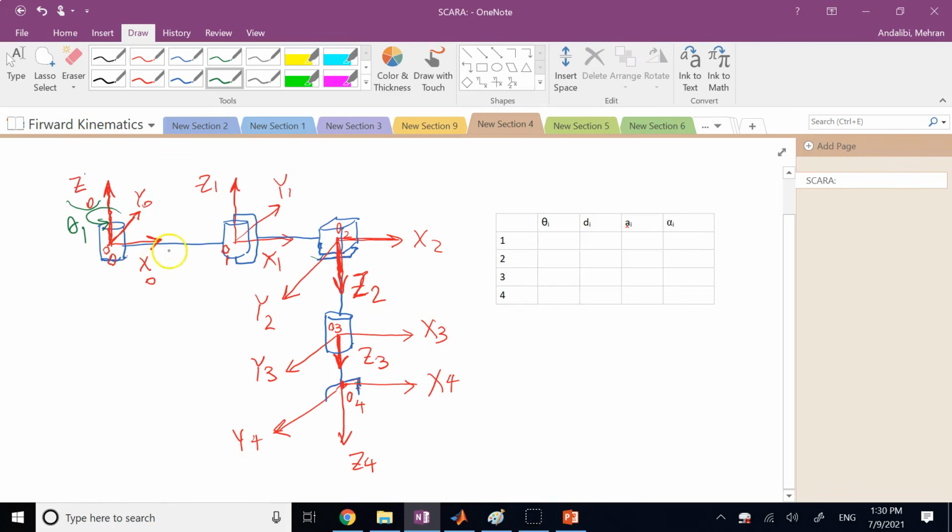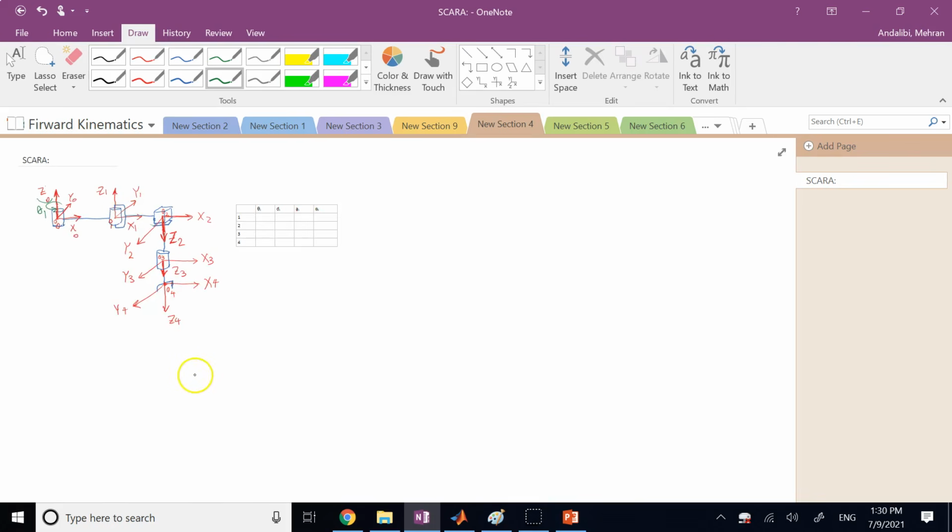In general, when this robot acts, if you look at this from the top, so this is your frame 0, then it starts rotating. This is going to be your second rotary joint. Okay, so if you look at it from the top, as I said, this is your x0. Y0 is like this. Z0 is out of the plane toward you, which I use this symbol to say. Then frame 1, again, Z1 is out of the plane toward you, but now your X1, which is along the member, is going to be like this.